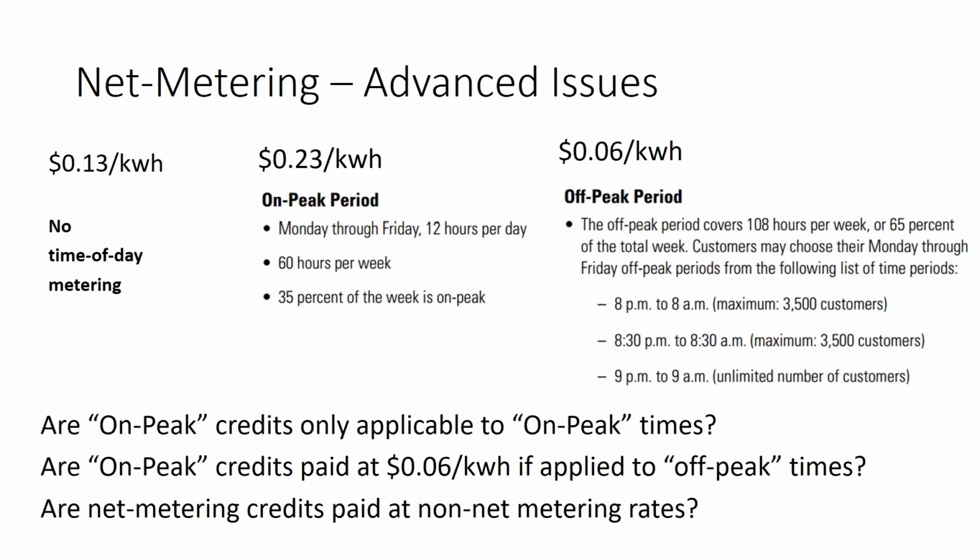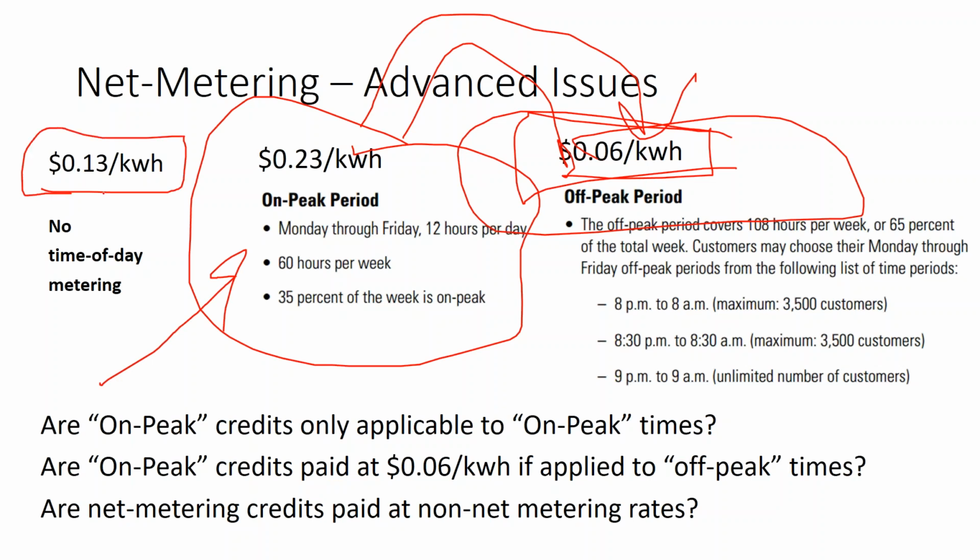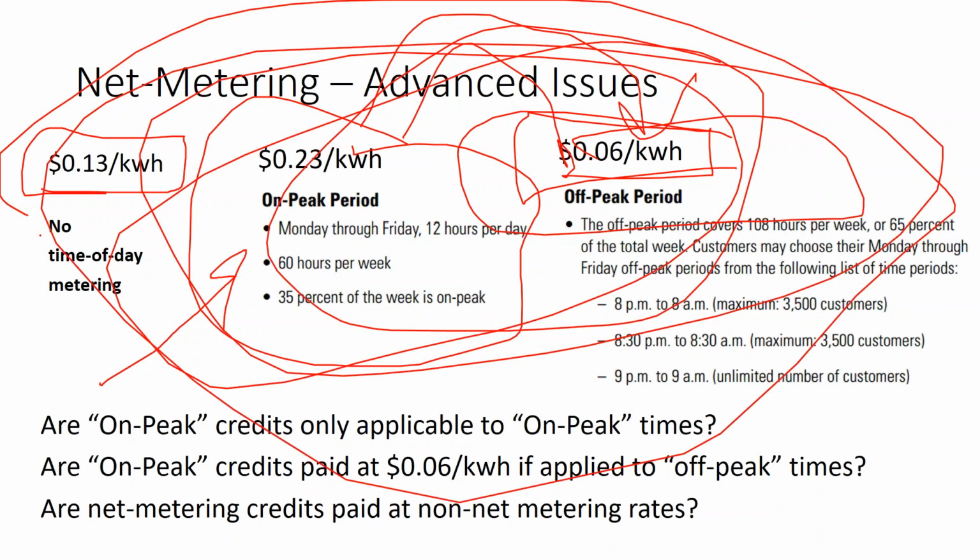But net metering fundamentally is not a perfect policy, because what it says is you're entitled to retail credit when you outflow onto the grid. So what's the definition of a retail credit? If I'm outflowing at peak times and then I go to off-peak for my credits, is that fair compensation? If the value of off-peak electricity is a quarter of peak electricity, is getting retail credit fair, or should I be net metering at the peak rate versus the off-peak rate? Or is the utility just going to net meter me at their retail value of electricity, regardless of what kind of individual rate structure I'm on?